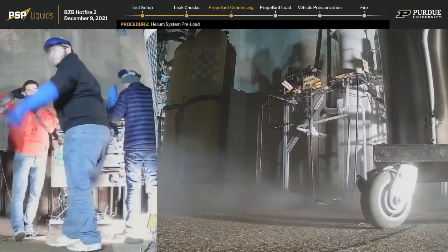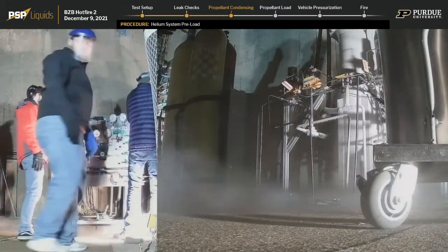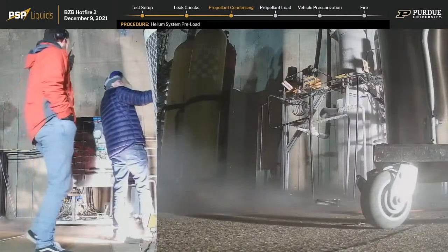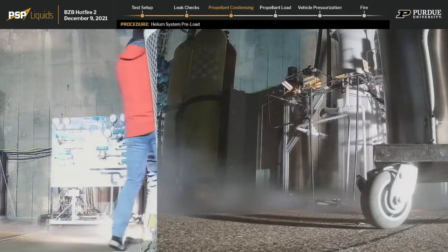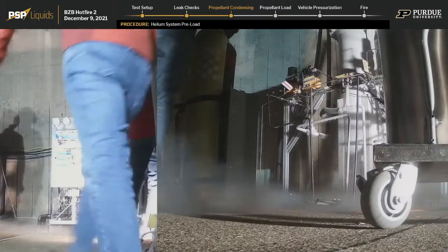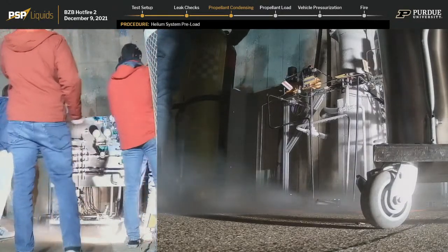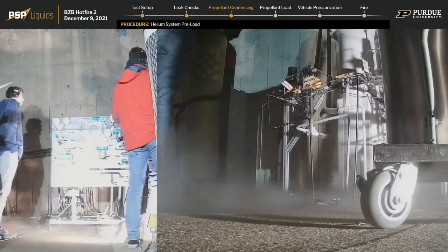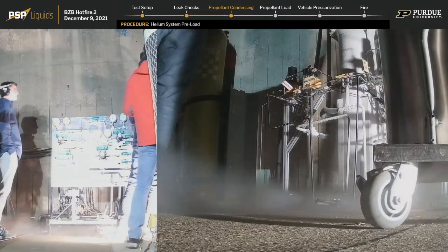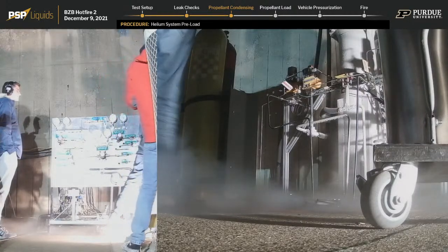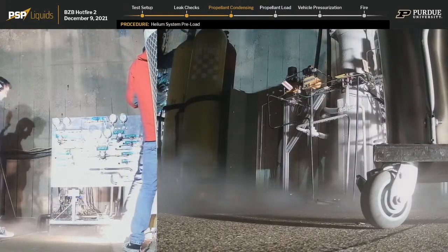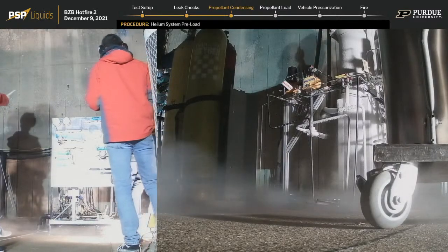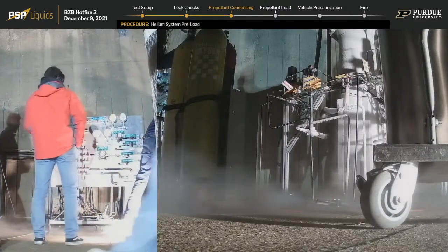So the first thing we do is, depending on whether it's an abort or a nominal finish, we have a different set of procedures that we run to make sure that the system is in a safe state. MV HE02, the helium bottle is open. Over. Copy, go ahead and open MV HE03, the other helium bottle. Over. So safe in this context means propellant is offloaded from the vehicle, either by boiling off or by venting. Yep. It means that we don't have any pressure in the system, and that operators are safe to approach the vehicle. Right. That's really what we're looking for in a safe system.